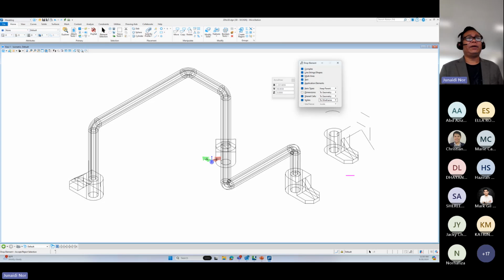Can I save a model as a template if I will ever need the same profile in another file? So that is called a library. Yes, you can. I want to save my time, so next time I can just insert it in AutoCAD. We call it insert. You save it with W block. In AutoCAD, you use W block and save it into a single file.